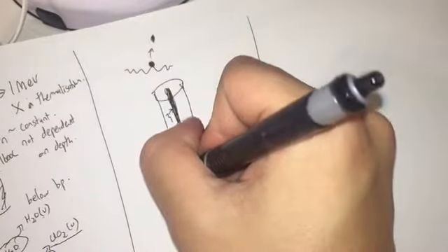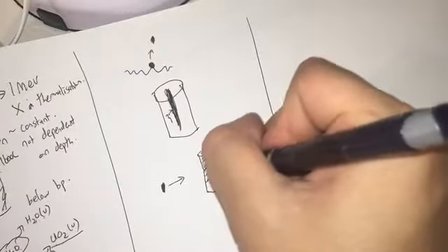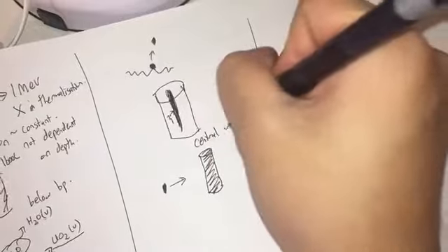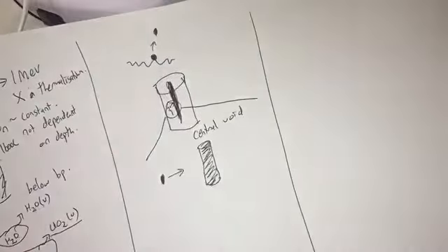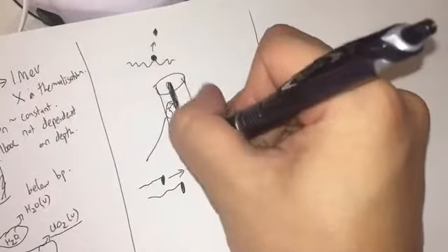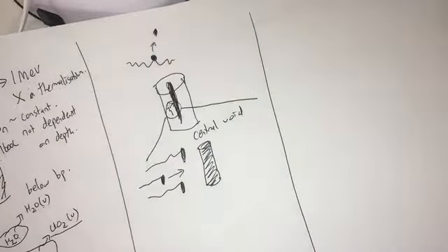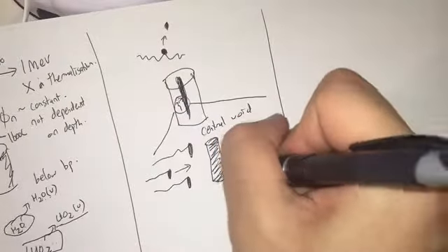When the pores migrate towards the central void, I'm enlarging this part, they tend to leave a kind of trail behind them. So in the fuel microstructure, you'll probably see something like this. These trails can be seen under a microscope, and with many of the trails tracing towards the center, you have something like this.